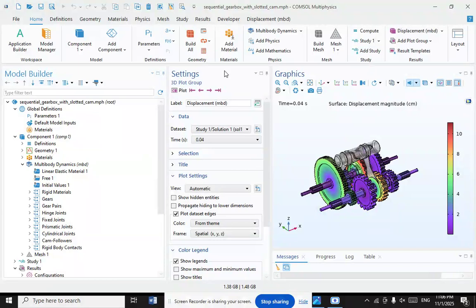Vehicles with manual transmissions use a clutch to manage the linkage between the engine and the transmission and decouple the transmission from the engine during gear shifts. And when the vehicle is stationary without a clutch, the engine would stall anytime the vehicle stopped. Changing gears would be difficult. Deselecting a gear requires the driver to adjust the throttle so that the transmission is not under load, and selecting a gear requires the engine RPM to be at the exact speed that matches the road speed for the gear being selected.